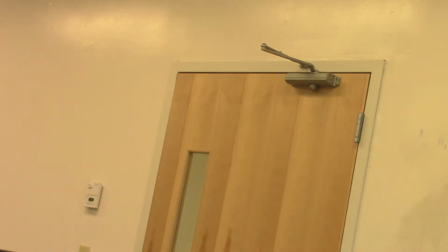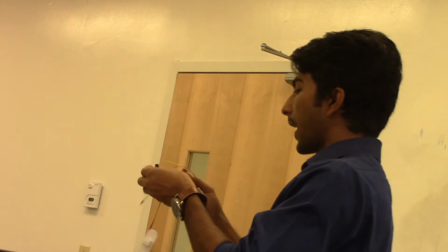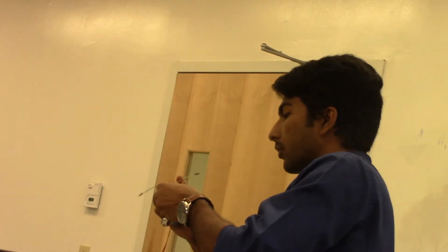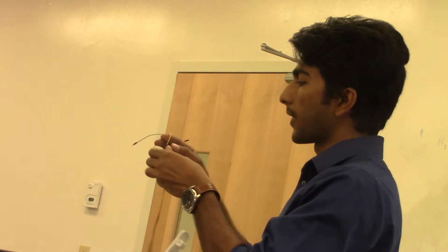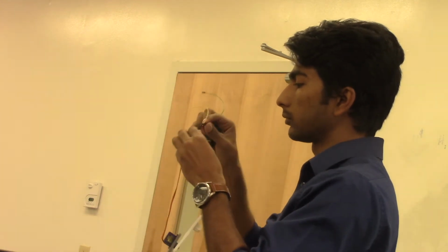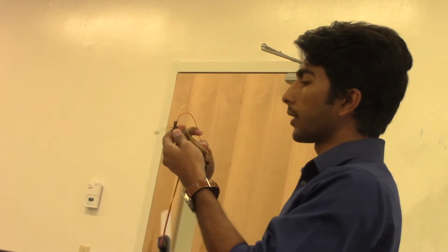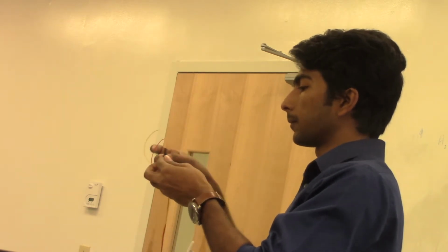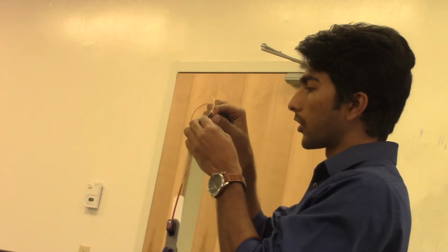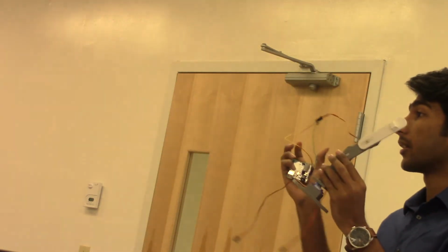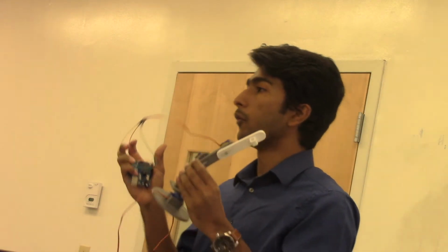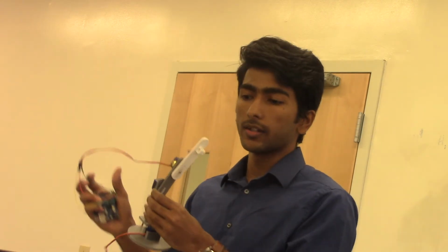So I can connect these 3 pins to one of the servo motors. The same way, I can connect the ground to the black wire here, sorry, the brown. And then the red one goes to the red one here. And then the green, the signal cable, will be connected to the orange one. So this should be your initial connection. This I just connected for the first servo motor, but we will use a breadboard soon to connect the different servo motors.